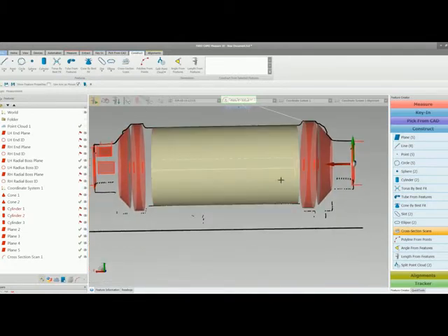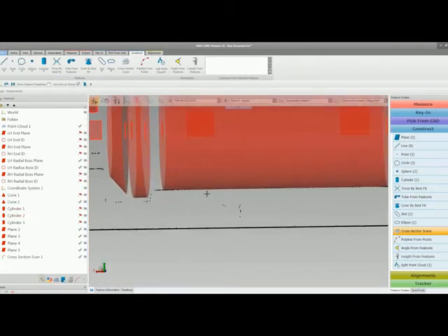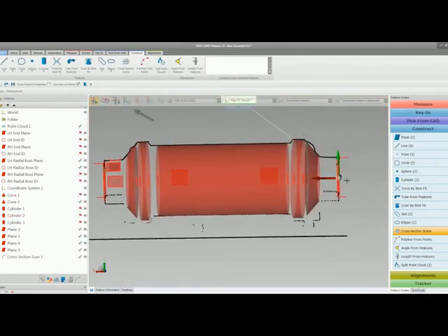Also, rather than cutting just one section, I would usually cut a couple of sections so that when you do revolve it, you can see that you've got your center of rotation right, so that the surface rotates through every single cross section. That one cross section rotates through all the other cross sections. If it doesn't, then that's a sign that your axis of rotation isn't in the right place.